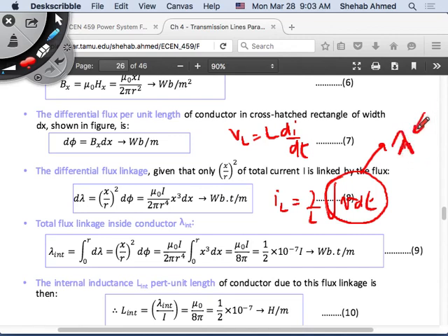So if I calculate the flux linkage, and I have the current flowing through either the small area, which is Ix, or the full conductor, which is I, then if I know lambda and I know IL, the inductor current, I can calculate the inductance. The relationship between them is inductance. Okay, that's where this equation on top comes from. It's just from the basic VL equals L di/dt. So any questions on this?